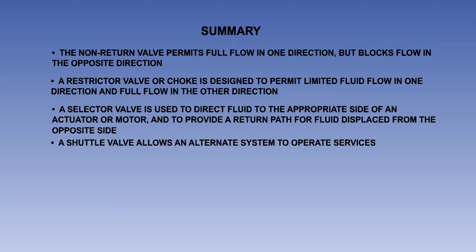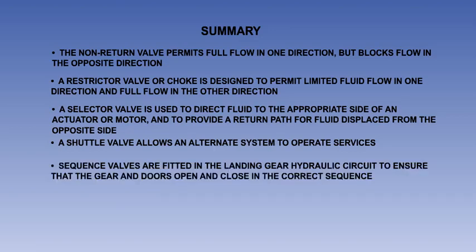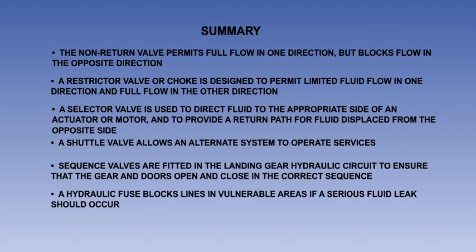A shuttle valve allows an alternate hydraulic system to operate a service. Sequence valves are fitted in the landing gear hydraulic circuit to ensure that the gear and doors open and close in the correct sequence. Hydraulic fuses block lines in vulnerable areas if a serious fluid leak should occur.